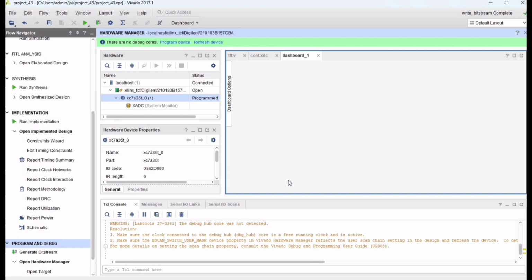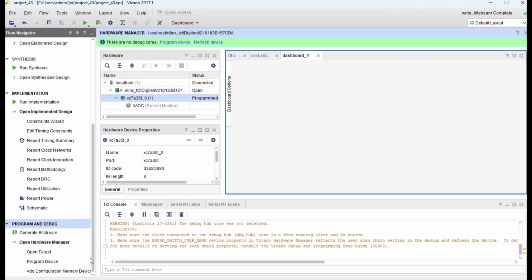So you can see, you have to connect the Basys board using that probe to CPU, and you have to assign two input pins. One is reset and T. Clock is already there in the Basys board. Okay, so the clock is of very high frequency. So you have two outputs, one is Q and Q bar.